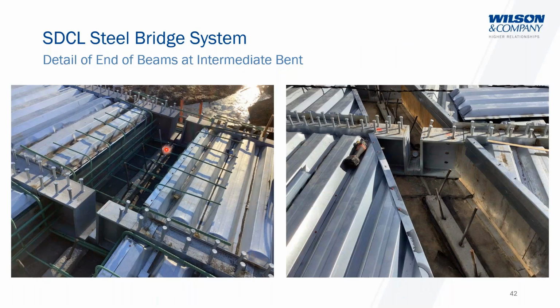So in between the girders themselves, that was one long plate across the entire width of the concrete diaphragm. Here on the left side, you can see we had a pretty significant change in width between in-span and mid-span, but yet again, that didn't change the size. We didn't change the width of the block to accommodate, to make sure they were both the same on each side. We just went full width on all of them just to simplify that detail.